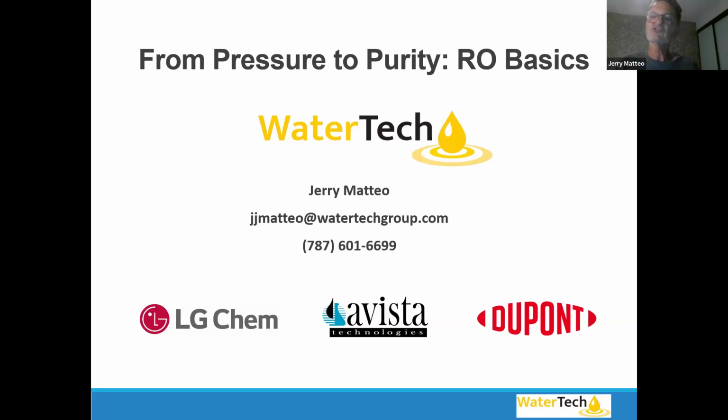But if they're in the concentrate, remember I told you in ocean water, where are you going to send it? Let's say you've got a 10 million gallon per day desal system. The concentrate goes back to the ocean. So we'd have to do something. The membrane will probably reject the microplastic, but it'll now be in the concentrate. Where are you going to put 5 million gallons per day of concentrate? So it goes back to the ocean. So that's a very good question, because you can concentrate it in the RO, but you still need a way to get it out of the concentrate. I hope you catch what I'm saying.